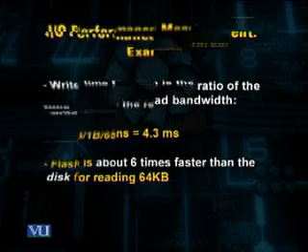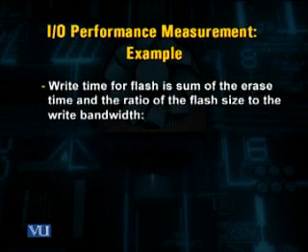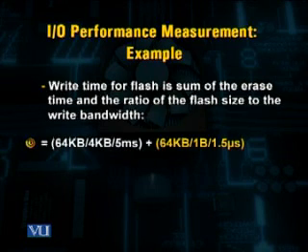Now the write time for the flash is equal to the sum of the erase time and the ratio of the flash size to the write bandwidth. We know from the given data that the erase time is 5 milliseconds for 4 kilobytes.